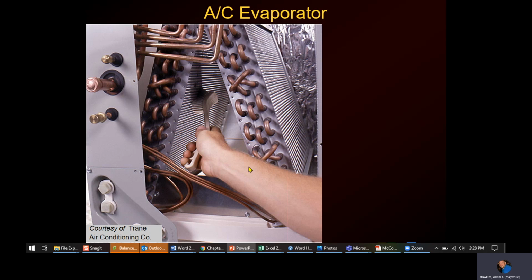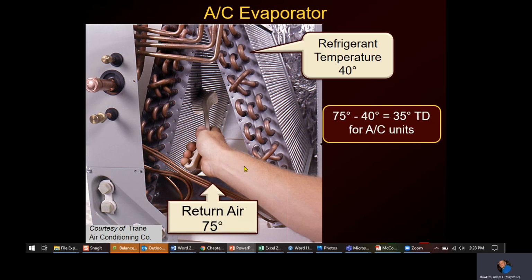All right, so most of your air handlers are using an upflow configuration, which means they're pulling or inducing air through the coil by the fan being on top of it, pulling it from the return into the supply through the coil. So your coil's under a negative pressure. In the case of furnaces and maybe some other types of air handlers, the coil may be after the fan. If that's the case, it's under a positive pressure. That's a forced type setup. So that does make a difference, and that can come into play.